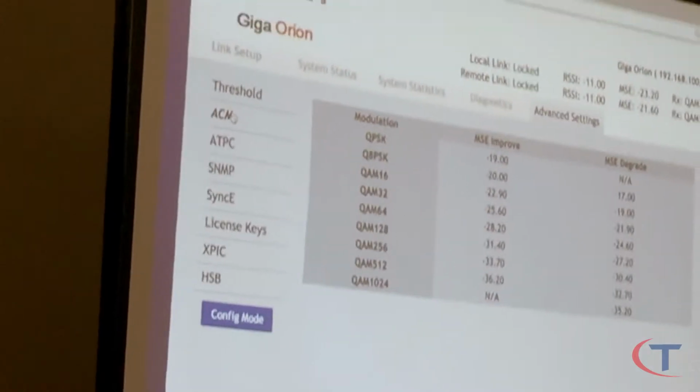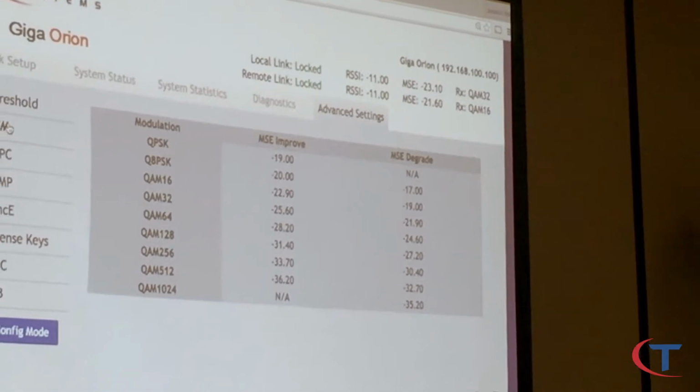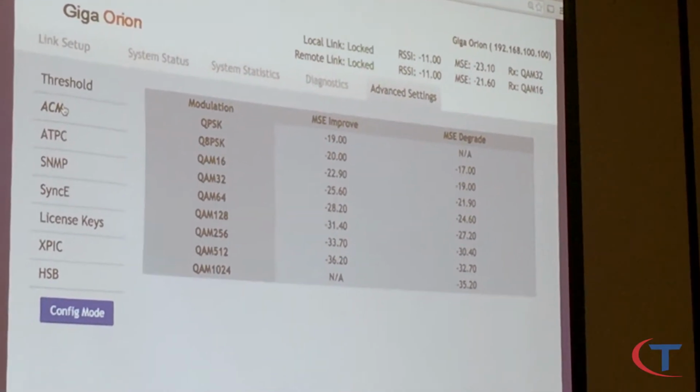And you're not in config mode. No, but those are not adjustable values. Those are. They are. I thought they were. Yes. Okay. But this is what happens. We pre-configure them for you because the threshold is the best we can actually configure based on the ODU. If you change them, let's say you're in a really rainy environment or really high temperature area, if you mess with them, the worst thing that is going to happen is you're going to get BERs because the ODUs are not going to be able to handle the modulation rate. So that's what I recommend, just leave them alone. If you ever change them, just make sure you don't have BERs or FBRs. So that's the first thing. You better have a good reason to change it.